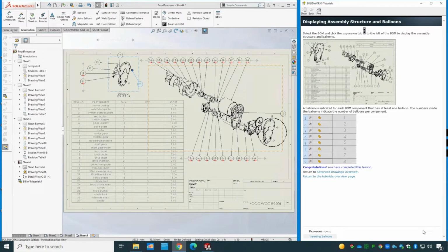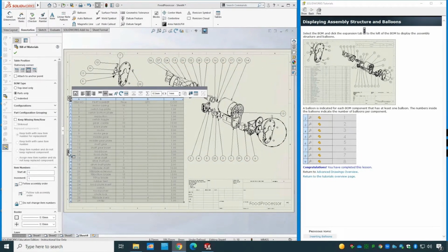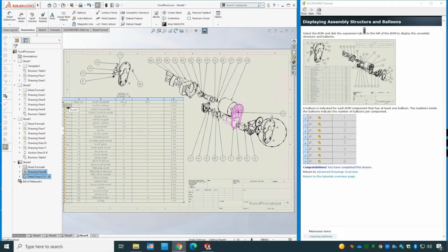And let's check the assemblies. So once I click in here, there is this icon. If you click on that, I can see the list of the part itself. You can see it would be highlighted. I can check the balloon of it. For instance, this one is a 4, that's why the balloon is 4. This one is 5, that's why the balloon is 5. That's why we have it, because once you print this one out, they won't be able to see this one.